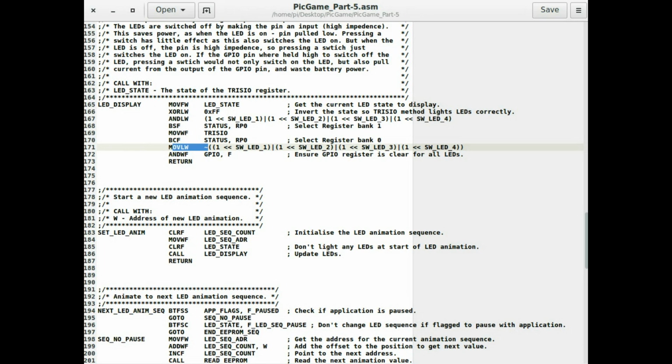And then this is slightly more logic. I'm doing the same as I did up above to select just the LEDs, but then this tilde sign inverts it. So I'm inverting the selection of the LEDs, and then I put that onto the actual GPIO port here.